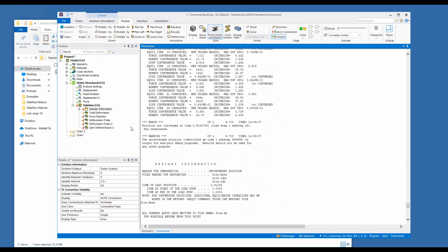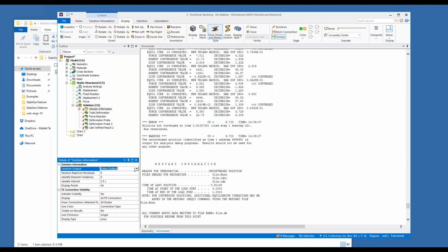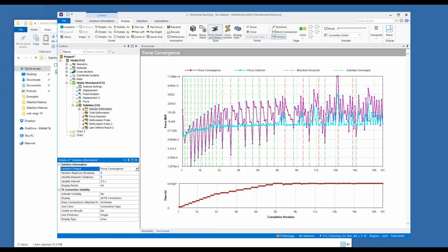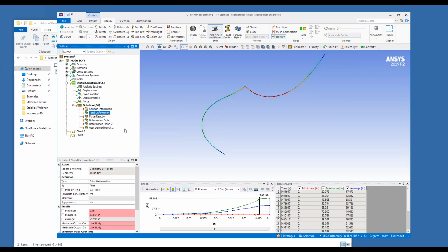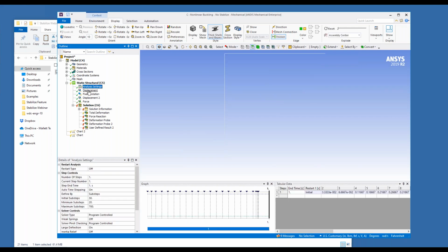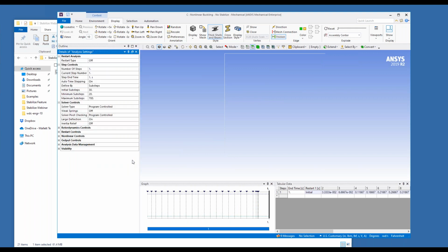So what to do? Well, I look at the convergence history for this particular problem, and we can see at some point here the code was struggling. You see delta t is very, very small here. It doesn't converge. Now, what to do? Well, we said activate stabilization. If I look at this deformation and say I want to take the last point and blindly, as a user, just go back and say, okay, go back, activate stabilization, which you see here.